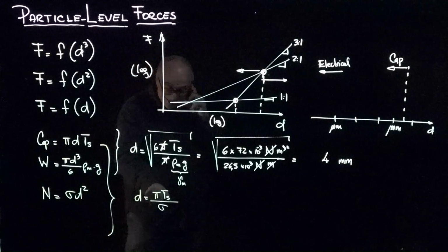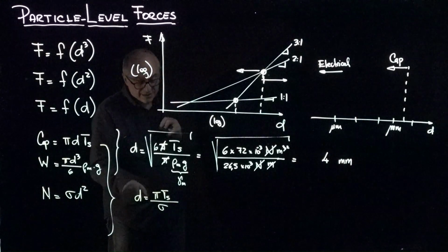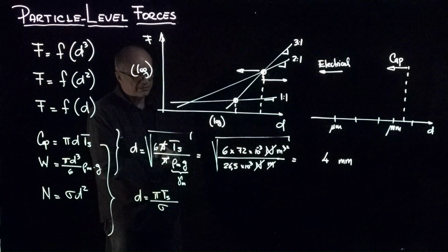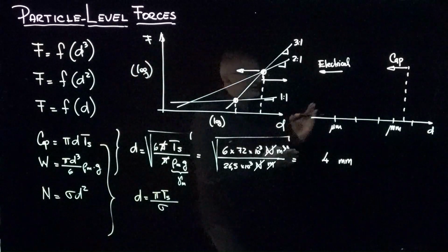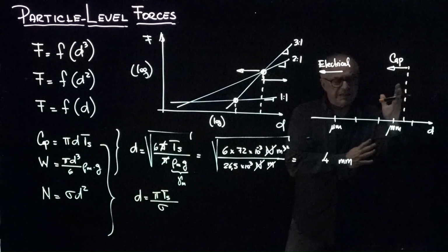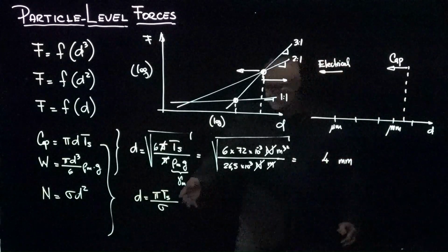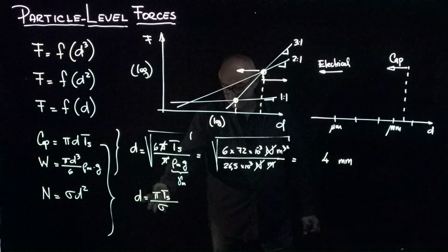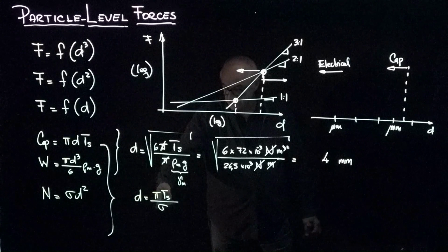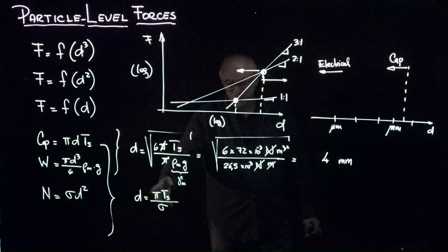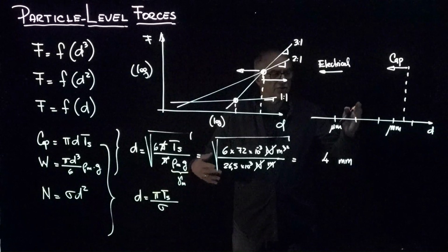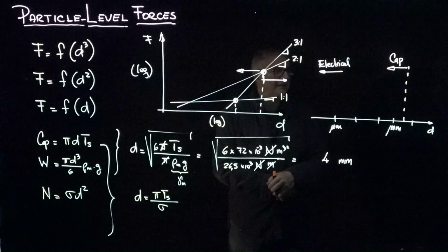So the higher the state of stress, the smaller the particles have to be for capillary suction to be relevant. This was the extreme case where we were competing with the self-weight of the particle, but really for a soil, let's say at 100 kilopascals, which may be 10, 15 meters for an unsaturated condition, then that soil will really have to be finer than the silt size to have the effect of capillarity.